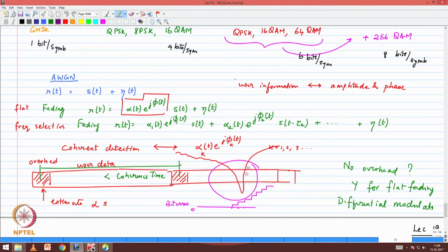This was more of a dramatic description of what changed. Usually what that means is within the coherence time, the change is small, but there is change. So again, it depends on the amount of Doppler that you have designed for. For example, I assume that my system is designed for Dopplers up to 60 kilometers per hour. So I have designed my periods with the appropriate coherence time.